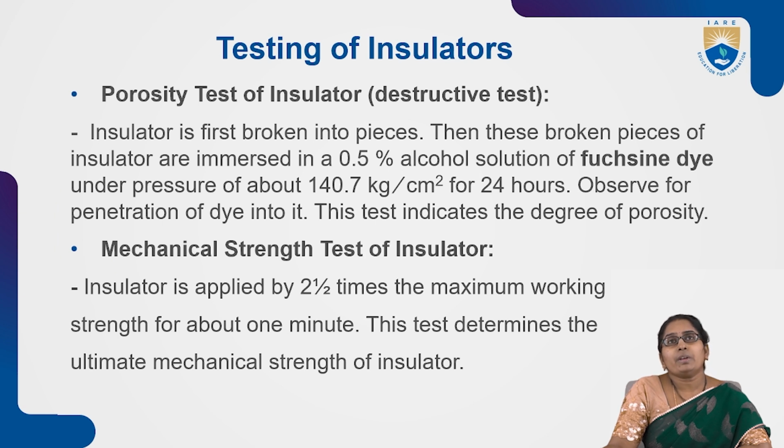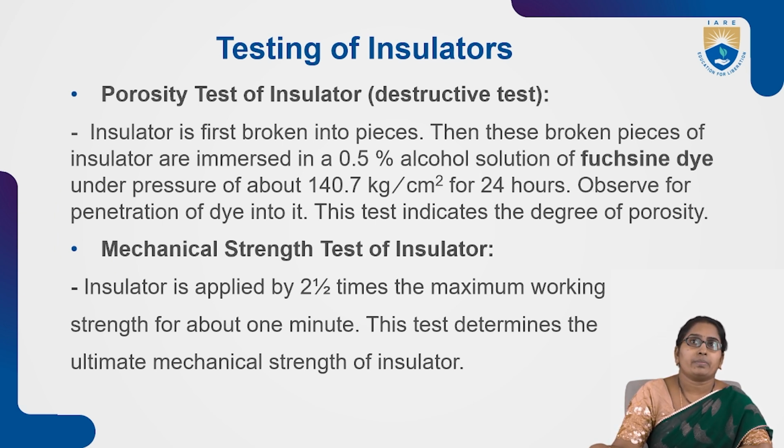And the next one is the mechanical strength test. In this, the insulator is loaded with 2.5 times the maximum working strength for about 1 minute.